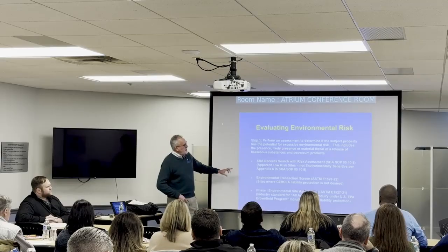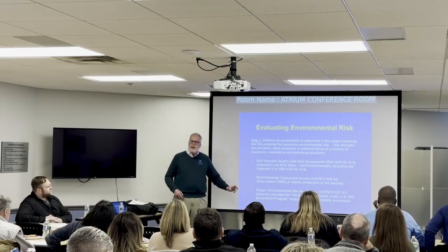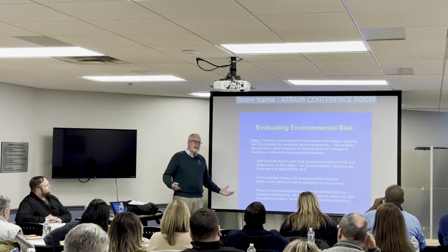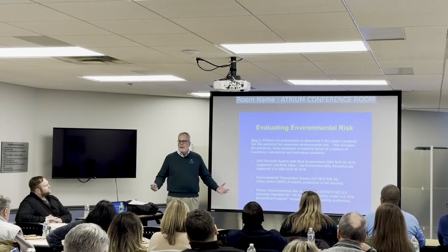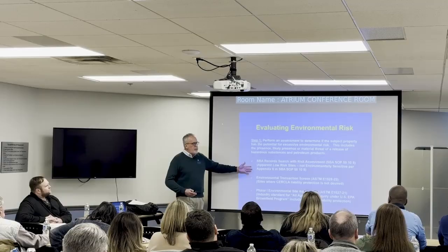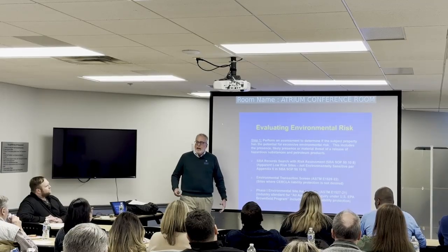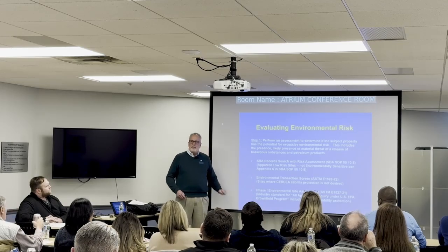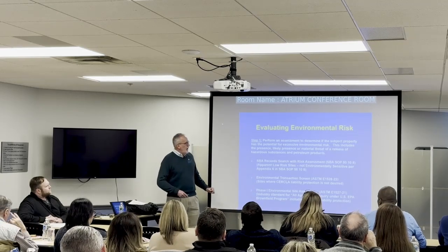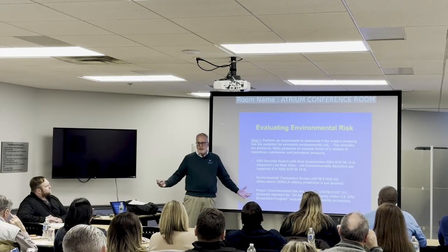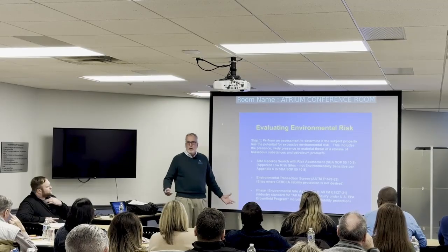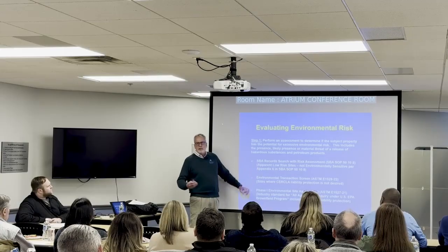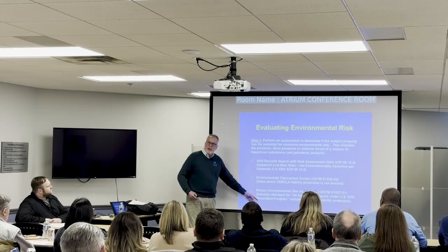So the SBA record search and risk assessment is a nice tool. When we first ran across it 5 years ago or so, it was like, wow, we don't really have much to go with here. Are we really going to render an opinion on a site we haven't physically stepped on? The key is to use it for the right properties. This is good for that dental office outside of a small town, or an apartment complex in a residential area that appears to have always been residential. If not, if you're next door to the gas station, the recommendation is going to be, well, go do a Phase 1 now.